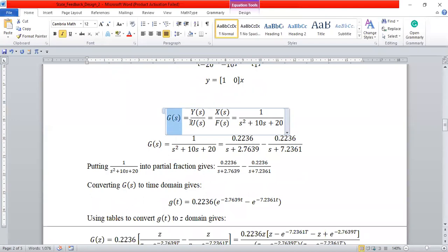discrete time domain because the way we've converted it, this is not the actual way the computer sees the system. So the computer uses, like I said, analog to digital converters and digital to analog converters. So a digital to analog converter is modeled by a zero order hold.